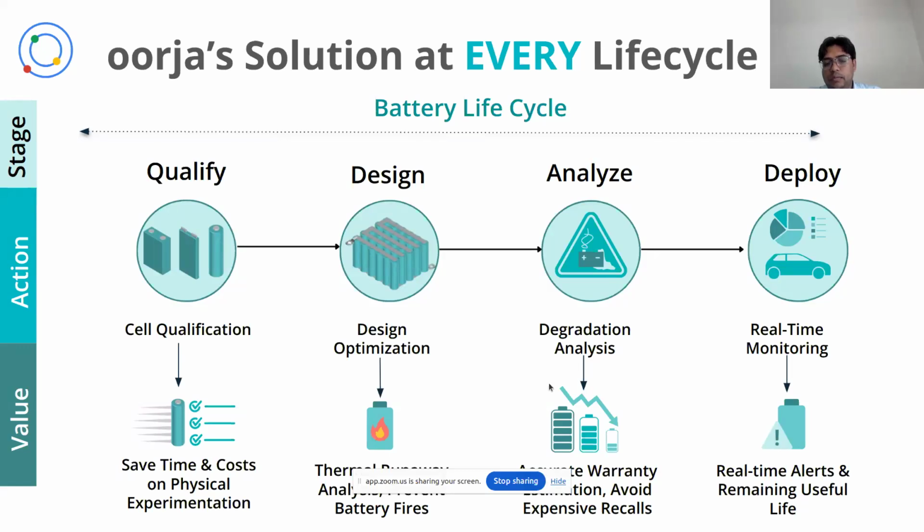On the other side, if you start by doing the physics modelings, the first challenge you encounter is that you need a lot of parameters which go into the physics to accurately model these batteries. And some of these parameters are the parameters which are used during the manufacturing. For example, it could be the transport parameters in the electrodes, electrolytes, as well as the material parameters of the constituents. And at the same time, you need to also look at the degradation models and get a hold of degradation parameters. Getting all of these things for a person who is not manufacturing the cell is very difficult.